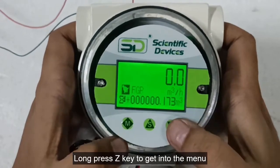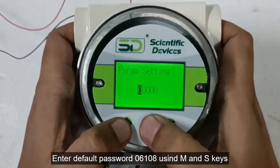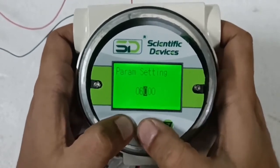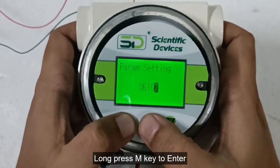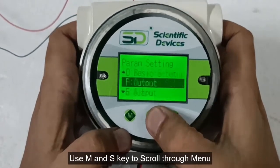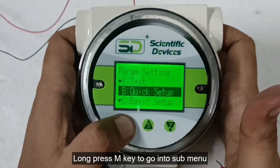Long press Z key to get into the menu. Enter default password 06108 using M and S keys. Long press M key to enter. Use M and S key to scroll through menu. Long press M key to go into sub-menu.